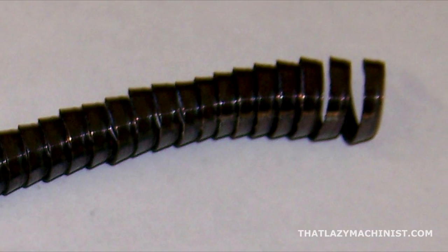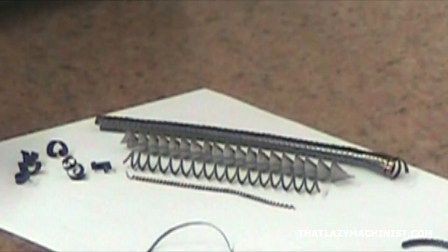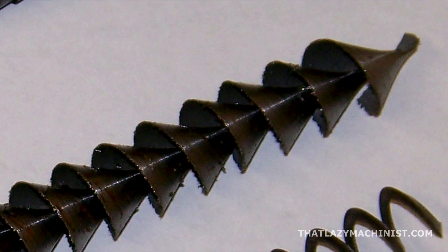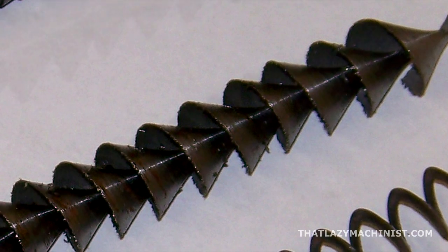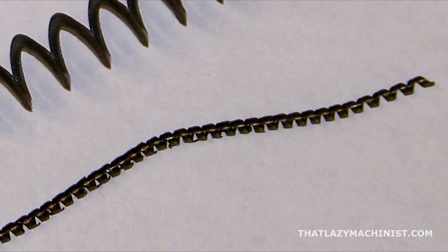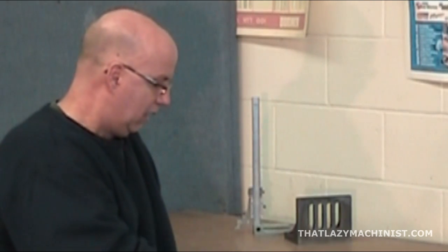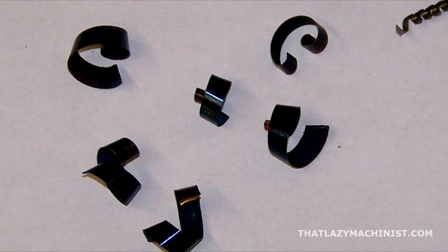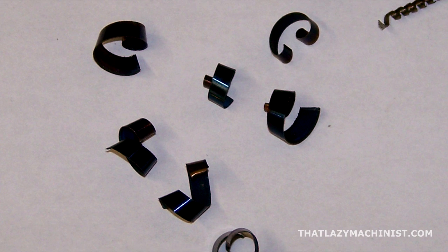Even though they're all continuous chips, I have several different examples here. The first one at the top here is a chip produced on the lathe with a carbide cutting tool. The second one is a chip produced on a drill press using a high-speed steel drill. The third one is produced on a lathe using a high-speed steel tool, as is the fourth one here, just a little tighter. These chips to the left here are continuous chips, but they are segmented continuous chips because they were produced on a milling machine. Milling machines have discontinuous cutting action.